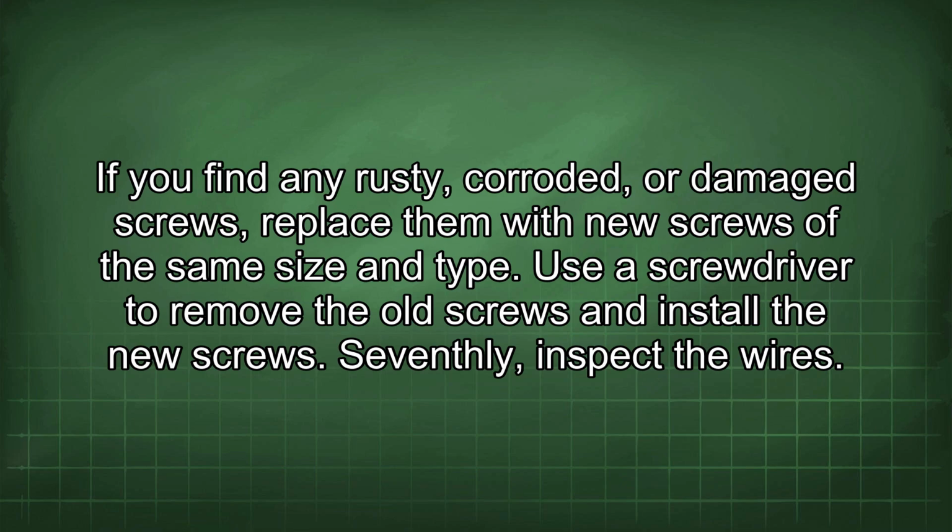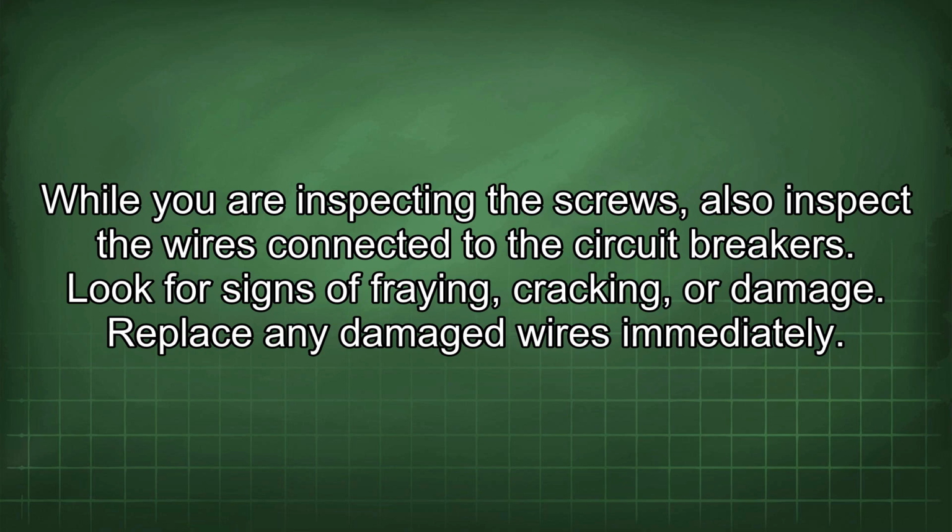Seventhly, inspect the wires. While you are inspecting the screws, also inspect the wires connected to the circuit breakers. Look for signs of fraying, cracking, or damage. Replace any damaged wires immediately.